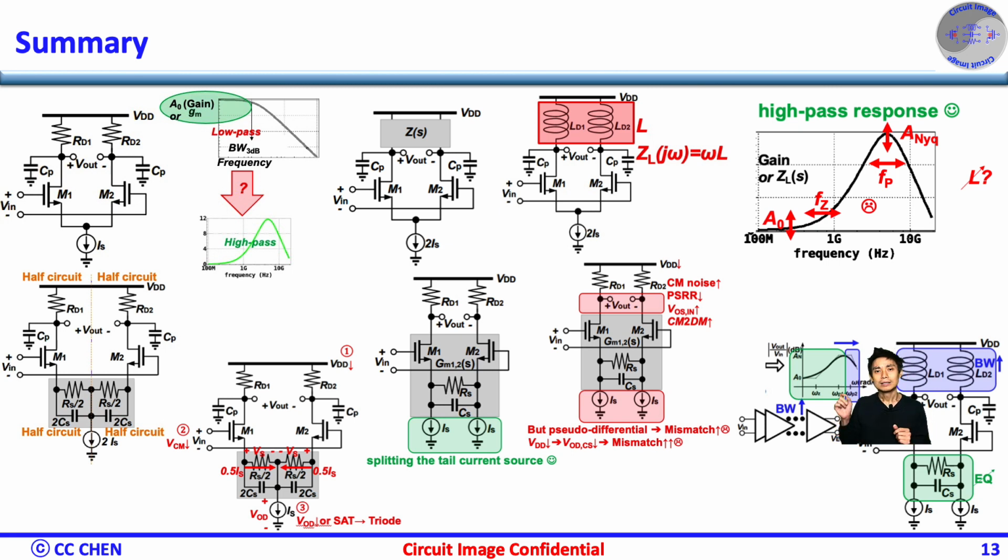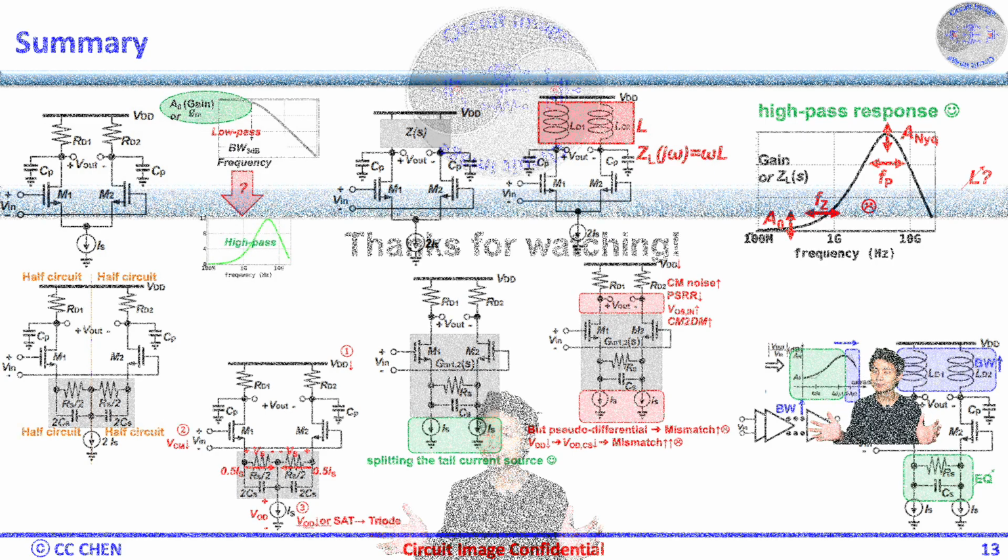Again, the shunt-peaking inductor is only for bandwidth enhancement, and the source degeneration CTLE mainly provides the flexible pole and zero response tuning for different lossy channel profiles with better linearity and maximum flat frequency response than the standalone shunt-peaking CTLE.